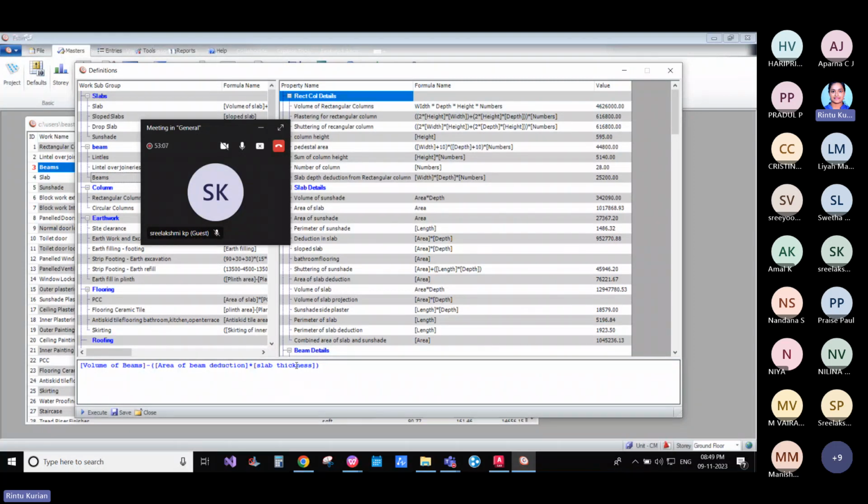This is because the quantity of slab was taken as a wall. So you will have to remove that thickness of slab from the depth of beam. So that calculation was done indirectly through this equation. So if you are feeling this was confusing to deal with, what you can do is come to definitions, read through the equation, try to apply it for an actual project manually, and if the calculation is not matching, then go to the property builder.